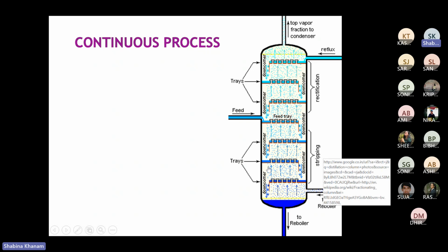Okay, now if you consider a single plate, not the complete diameter can be considered as the diameter of the plate. As you consider the baffle, a certain part of that baffle we consider as a cut. So that also you will see over here. And this will decide how much this distance should be, and this distance we call the downcomer section.